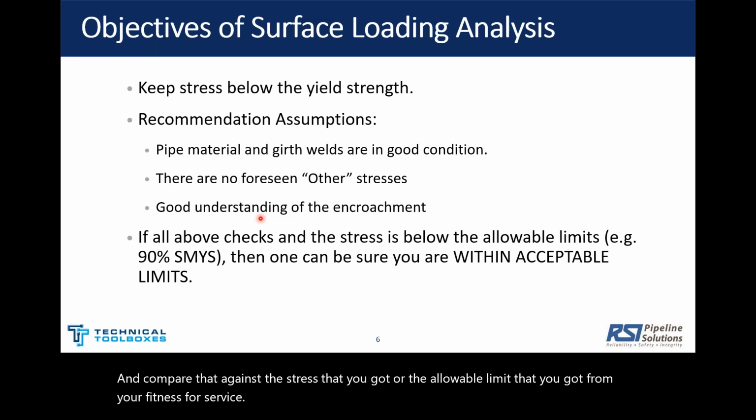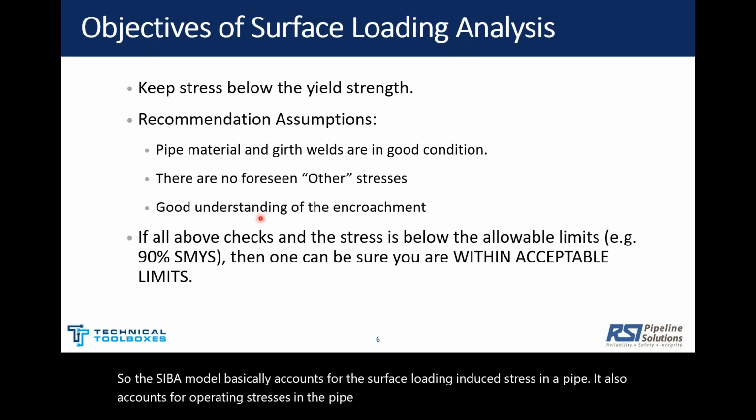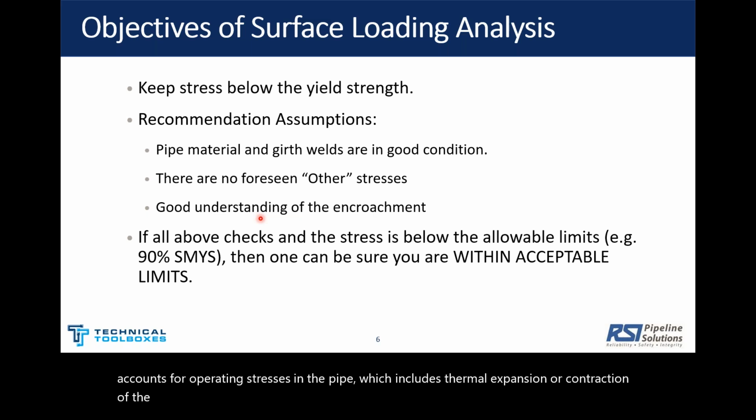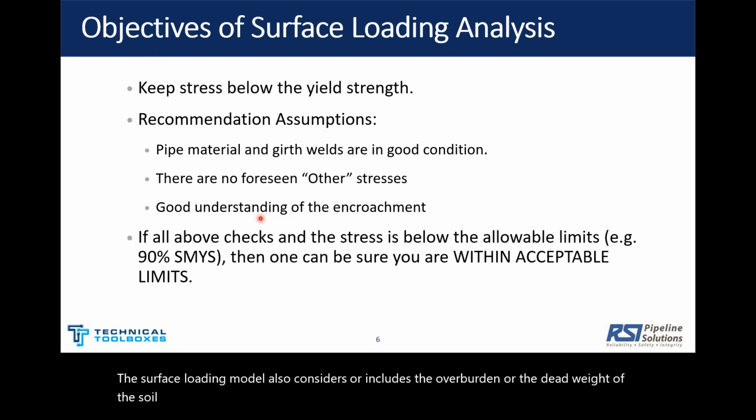The CEPA model accounts for the surface loading induced stress in a pipe. It also accounts for operating stresses in the pipe, which includes thermal expansion or contraction of the pipe, and the effect of the internal pressure, the Barlow equation. The model also includes the overburden, or the dead weight of the soil over the pipe.